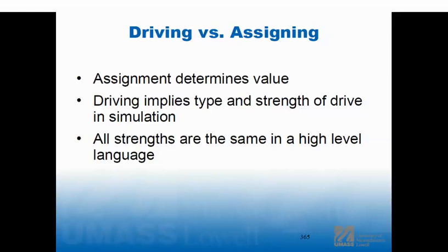So you may have to have a behavioral model of the I/O block during your behavioral synthesis. And then you don't put the real pads in because they're probably not ready until you do your gate level simulation at the end. So I don't think I explained this slide the way it's written, but that's the reality, what I just said, right? That a lot of times those pads are independent.